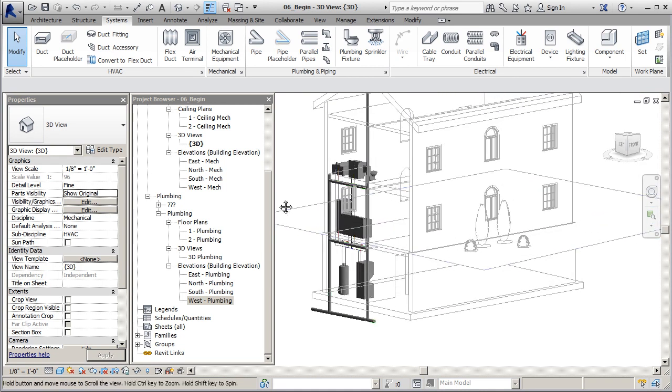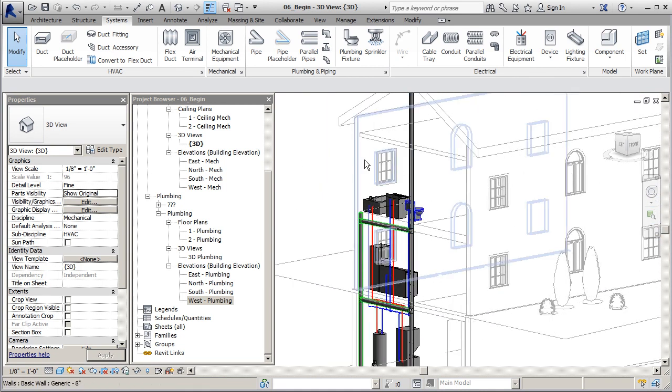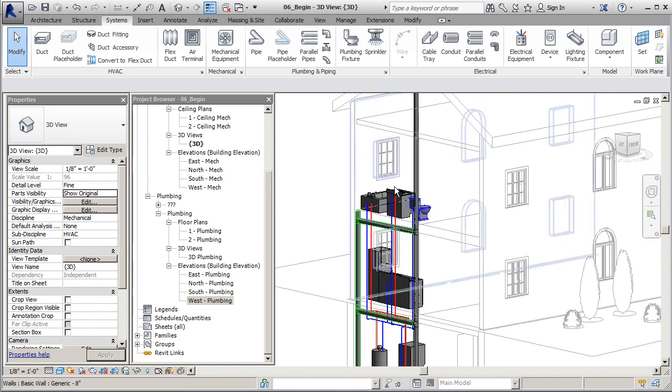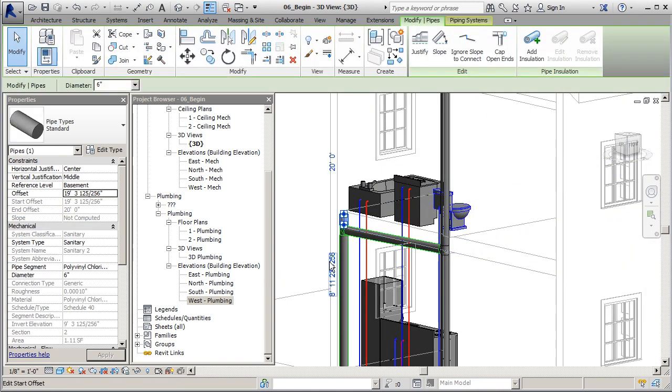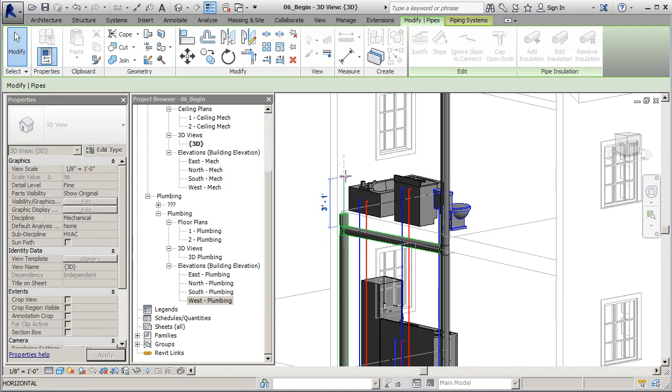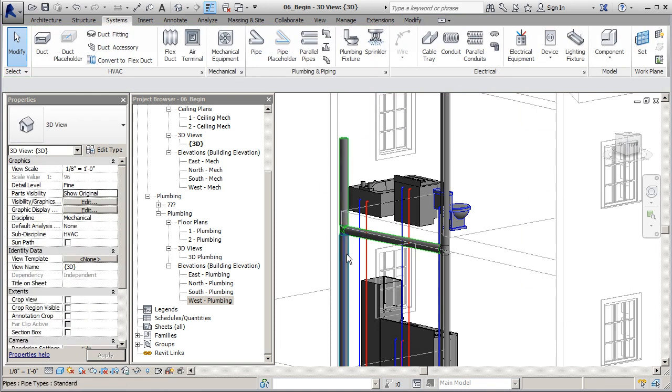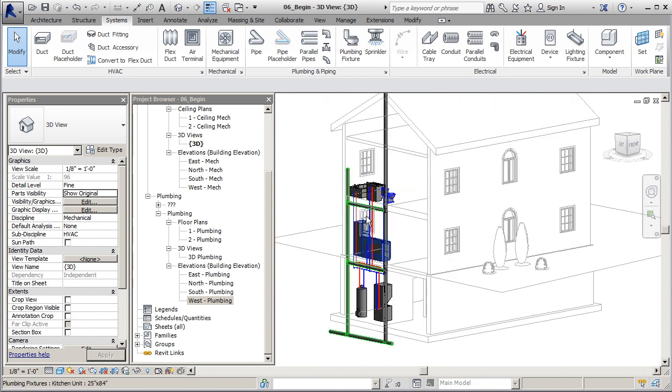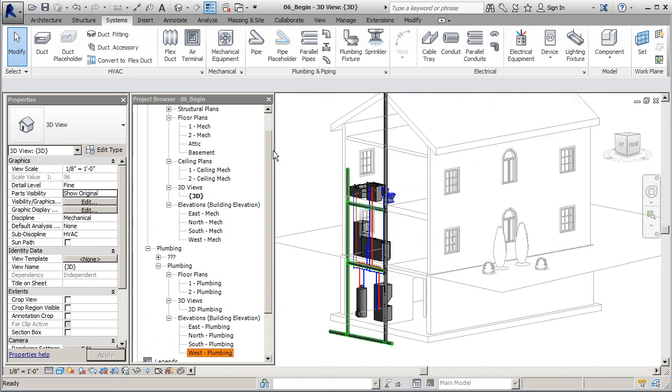So now let's add some ventilation so we can ventilate some of these fixtures, and I'll show you how we can go about doing that. Well, I know that we'll start here in the bathroom on top, so I know I'm going to need some extra length on this segment here because I want my vents to go about maybe 5 feet up, midway up that wall. So like we've been doing, I'm going to click on that endpoint, and I'm going to be mindful of that blue dashed line that lets me know I'm maintaining my slope and my position nicely. And I've adjusted that height there. And now I can jump to my second floor.